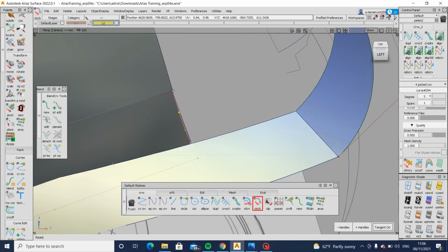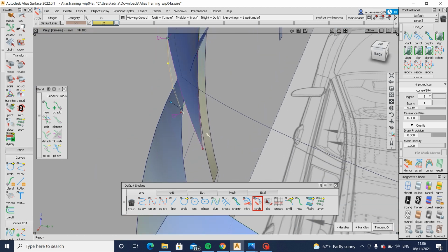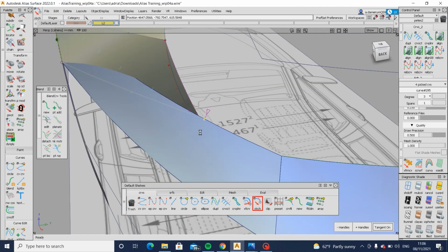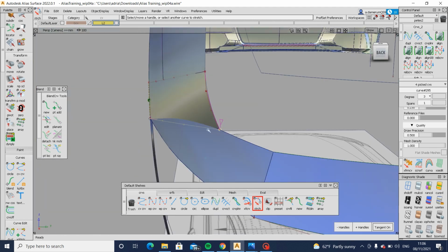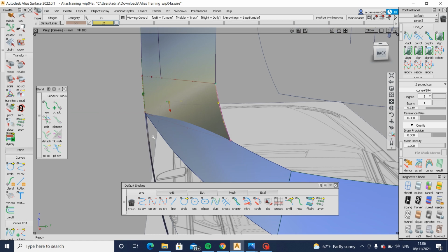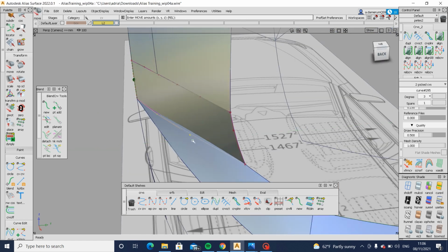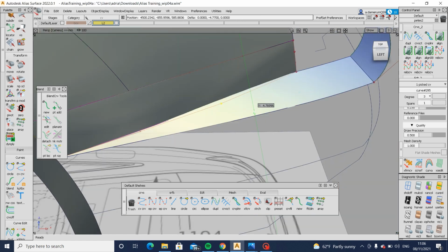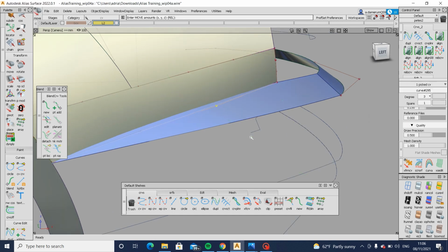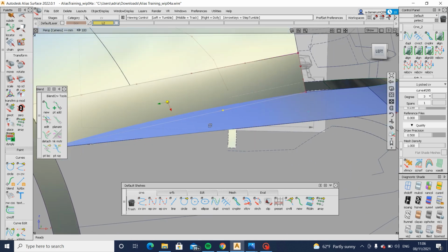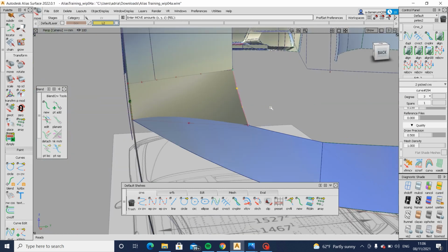We want it to kind of hit there, so let's build that curve to there. And then this, snap that to there. Oh, that's nice. But again, there's a positive break there. That's just because there's too much crown here. It's better. This now can come outboard. Here as well, outboard. This actually should come inboard a bit because there's a positive break. Yeah, negative break. And it's just about now playing with the CVs to get this condition right and this condition right, and also get the highlights looking right. Again, I think maybe it's just too round there.